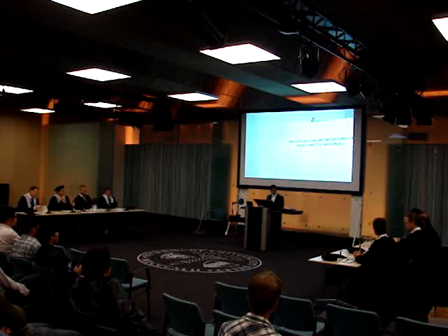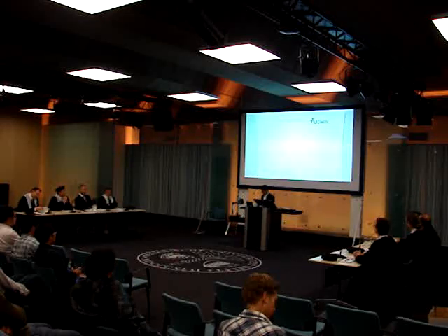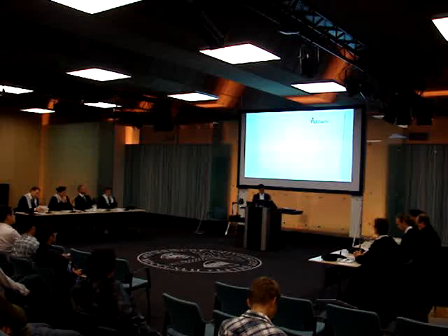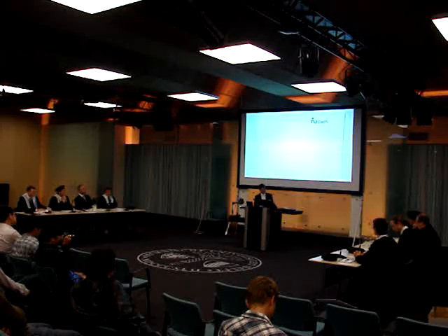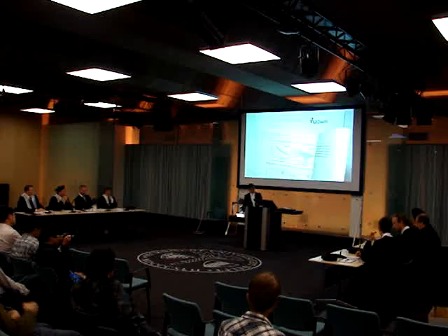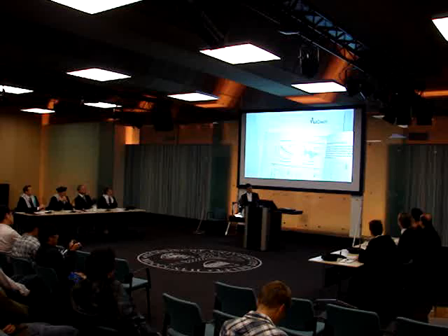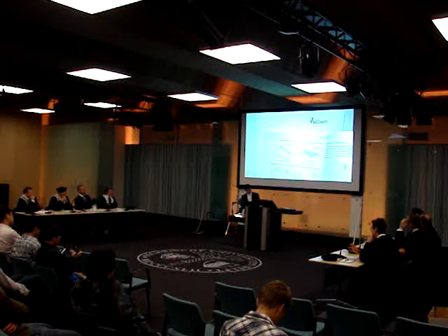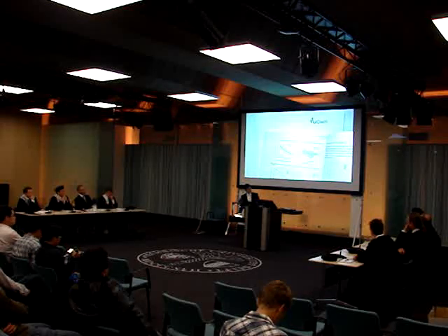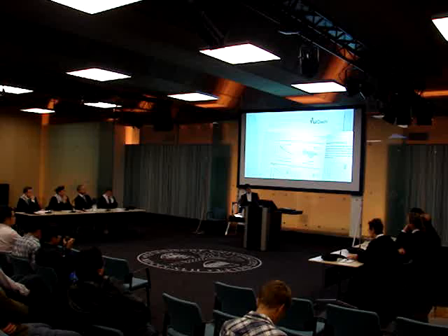On page 78, you're comparing the expectation and the deviation of the fracture energy using standard averaging and using failure averaging. You conclude from this picture clearly that standard averaging is not leading to an RVE because the expectation is going down as the size of the sample grows.